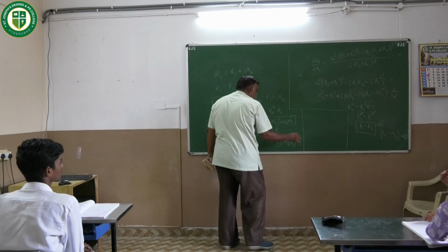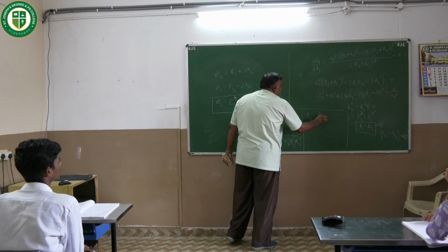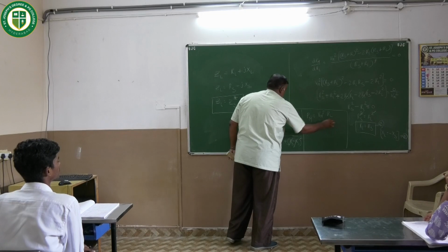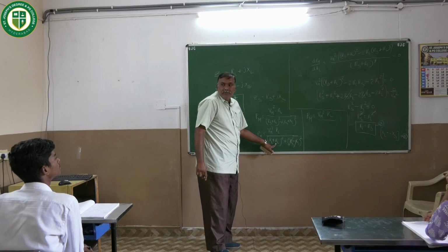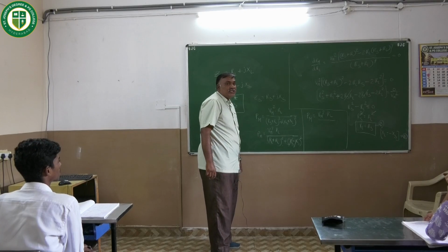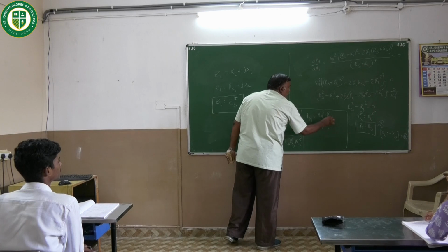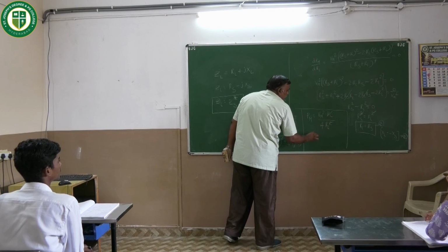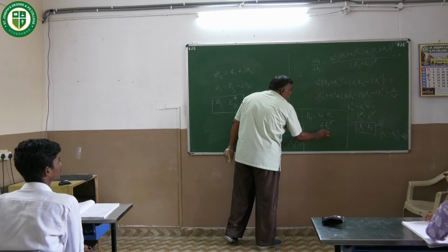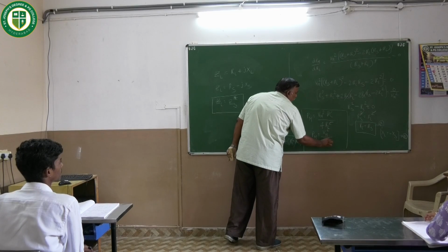So what you left out is Pm is equal to Vm square into RL. RL plus RL is going to be 2RL. 2RL whole square is going to be 4RL square. So 4RL square, RL square gets cancelled. So Pm is equal to Vm square by 4RL.